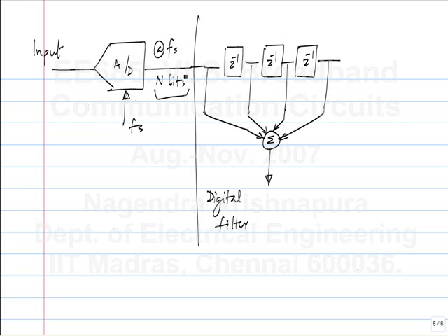Now if you go to very high speeds, basically it depends on how elaborate an equalizer you need, that is, how bad the channel is. If you go to a very high frequency, maybe the channel characteristic is not as bad, but it's just a high speed implementation. So you really cannot make a high speed A to D converter with a lot of accuracy. So there maybe 4 or 5 bits is enough.